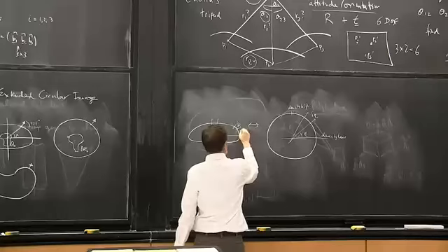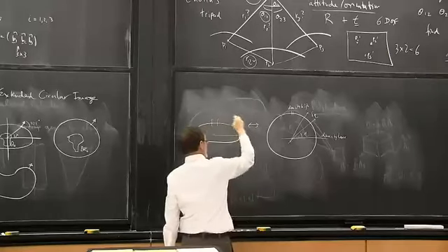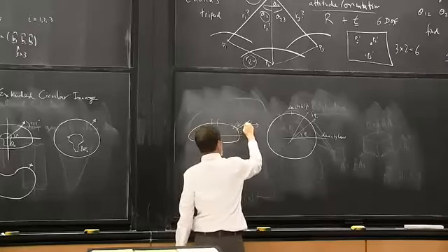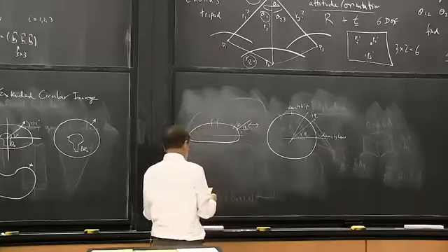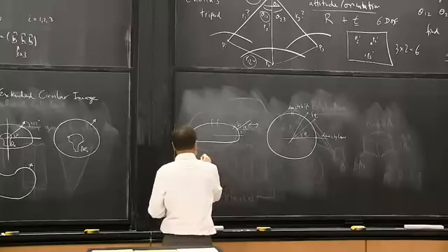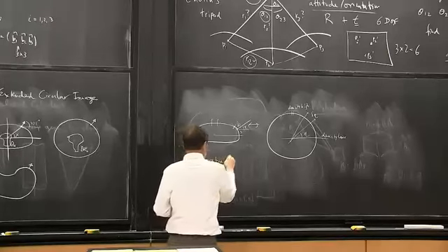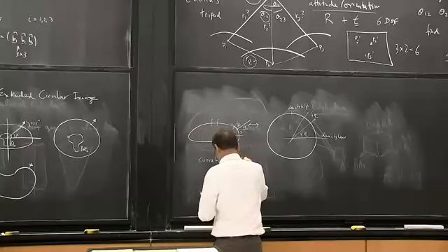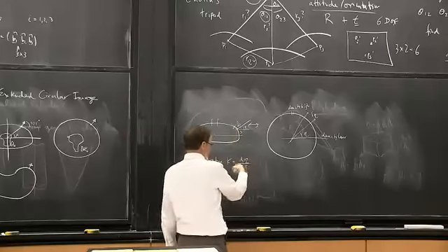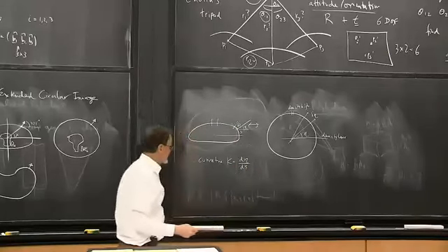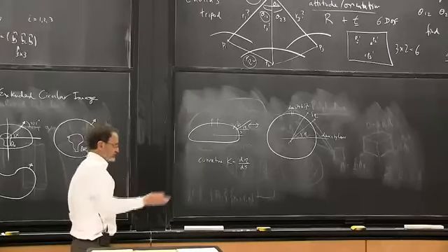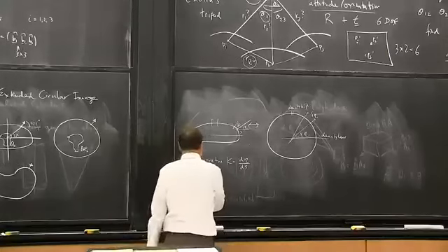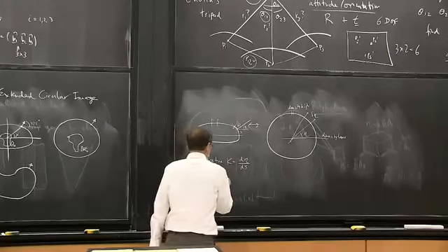So first, let's pick some arbitrary point. So S is the arc length along the curve from here to there. And then again, these normals are parallel, so this must be angle eta. And so what we're interested in is curvature. Let's start with that. It's the turning rate. Right? So, for example, if you're not turning, then k is 0. So it's the rate of change of direction, or it's the inverse, 1 over the radius of curvature.